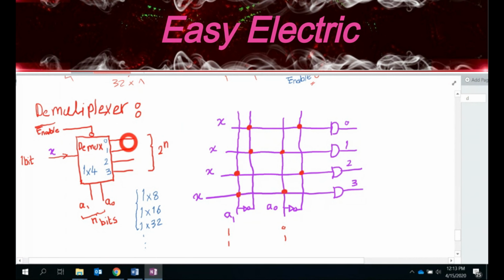So you tell me, whenever this enable is 0, similar with the other enables that we learned, the demultiplexer is doing its normal job. So whenever this is inactive, which is 1, all the outputs should be 0. How could I actually have that here? So you have one NOT here, and you call this enable. So whenever that is 0, the NOT is 1, and it should be connected to all of them, right?